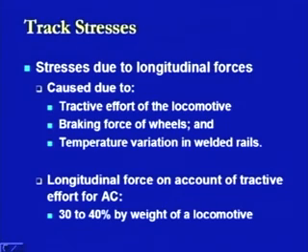One thing is that you are in a standstill condition and you start moving. That is where the tractive effort of the locomotive comes into the picture. Another thing is that you are under movement, you want to change the speed, or there is a braking effort, and therefore the braking force of the wheels will come into the picture. There can also be starting deceleration or acceleration conditions when the movement is going on on any of the rail sections.